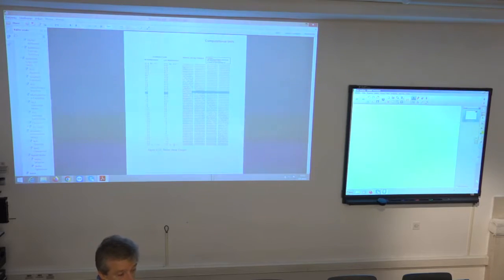Normally you would have a range of plus or minus 32 bit positions. But if, for example, based on some computation, it turns out that you have to shift 50 positions, then it's not a problem. You simply write 50 into this register, and it will shift the value out to a position that is not registered. The value in the final register will be 0.